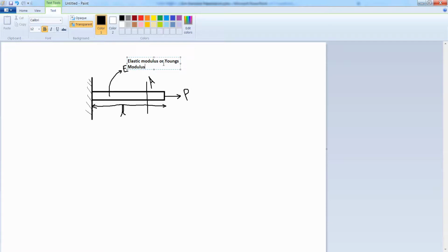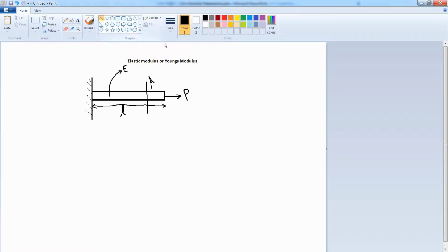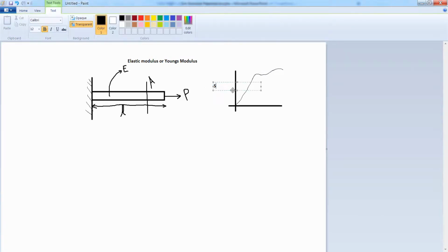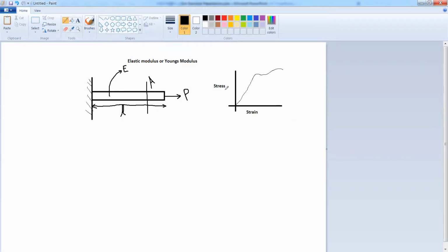Now, most engineering materials are characterized by a stress-strain curve. Now, this is generated by placing a metallic or plastic specimen in an ultimate tensile testing machine and recording its elongation or change in length versus force applied. Now stress is a measure of force applied and the strain is the percentage elongation. Hence the stress strain curve. Now a large portion of the curve is linear, meaning that in order to input this curve to the software, all you need is one number, which is the Young's modulus.